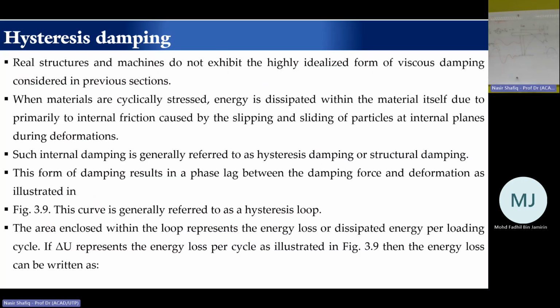Such internal damping is generally referred to as hysteresis damping or structural damping, like loading and unloading, right? This form of damping results in a phase lag between damping force and deformation, as illustrated in figure 9.